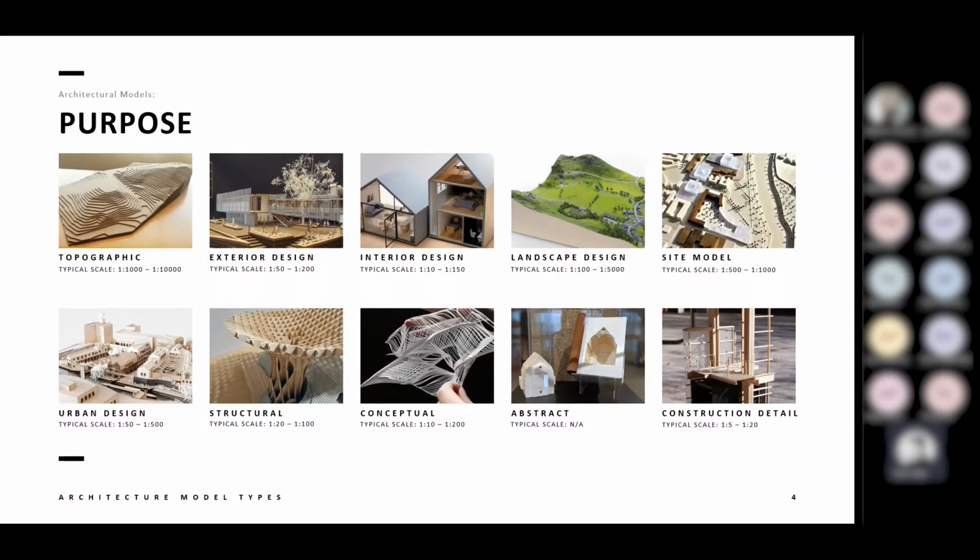We then move on to site model. So site models are, again, really, really useful. For these, you would usually have block massings around your site. So they're sometimes called context models as well. Usually you'd have block extrusions to represent the surrounding buildings, and these are usually up to about 1 layer around. So if your building's in the middle, you'd have 1 row of buildings all the way around it. You wouldn't usually communicate much further than that, unless there are multiple sites that you're designing.